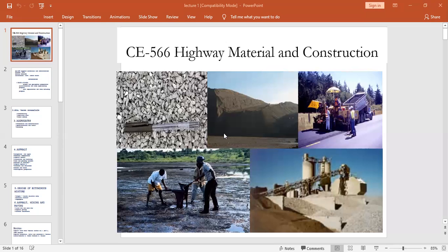and then what are other types of construction, because in topic 5 we said is the design of bituminous mixture, it means there is a production of asphalt concrete or bituminous concrete, then we lay it. But this is not the only way of having an asphalt concrete road. The other way is, we don't mix an asphalt concrete. Rather we lay it in different layers and then we compact.